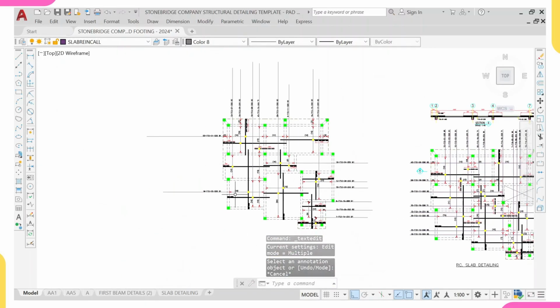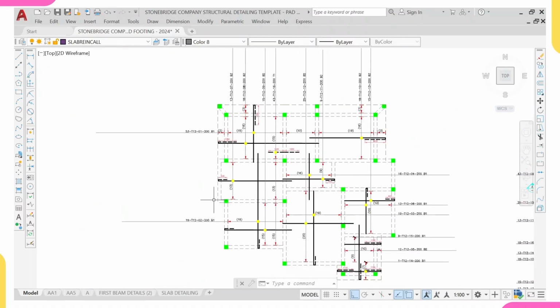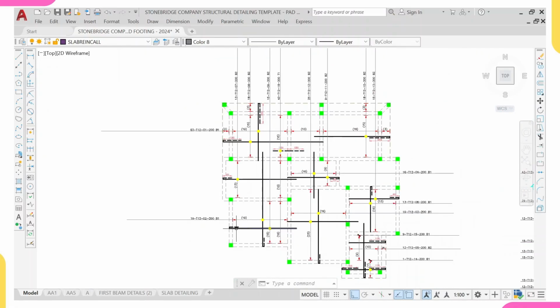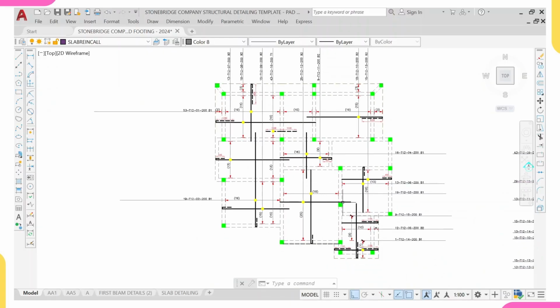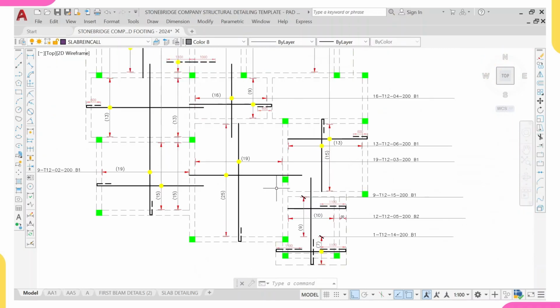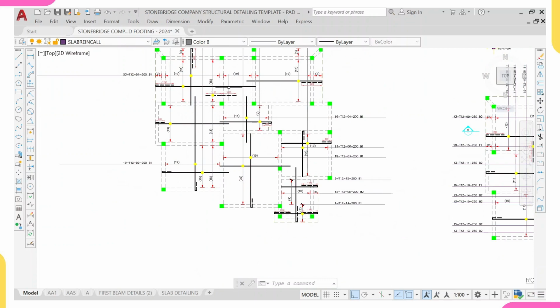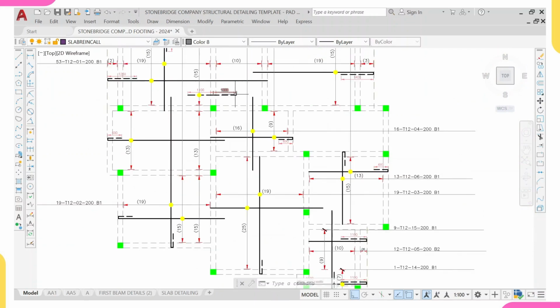Then this other one at the edge already has the top reinforcement, so we're done for this. This is not continuous. This is not continuous. And then this is a continuous beam. Knowing that this is a continuous beam, we already have that from here to here is 3,800 when we did this one, and 3,800 gave us 1,000.